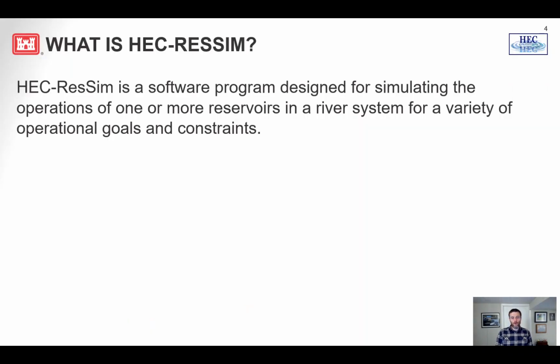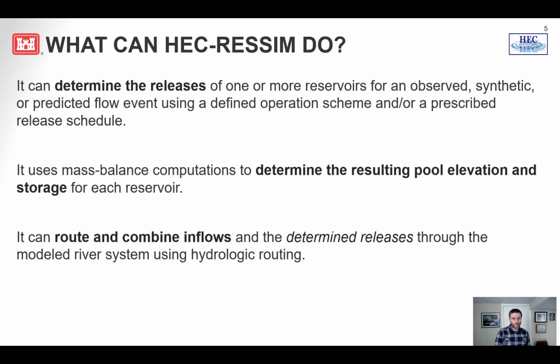So what is HEC-ResSim? HEC-ResSim is our software that we use to determine reservoir releases within a river system. So it's kind of an algorithm of rules and constraints that exist within a watershed to operate a reservoir. So a lot of times we use the water control plan to define those rule constraints, and then we operate that based upon some known inflows coming in that we would have from HMS for local flows downstream, inflows to a reservoir to determine an operation that would be suitable for a reservoir.